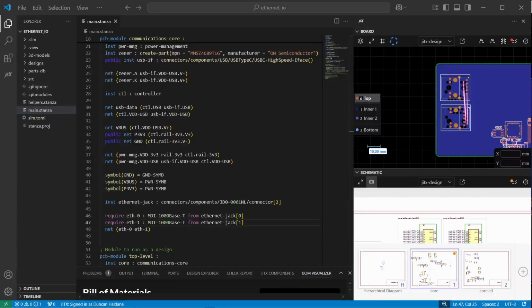So far, we've been routing differential pairs using the default dimensions. To enforce good signal integrity, we want to use impedance-controlled geometry and make sure that all of the skew, loss, and topology constraints for this gigabit Ethernet interface are met. We add these constraints in 2 parts. One is a substrate model for the stackup, which translates electrical properties like impedance to geometric properties like a per layer width. And then the second part is the electrical constraints like skew and loss for the interface.